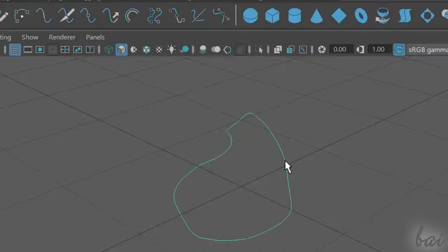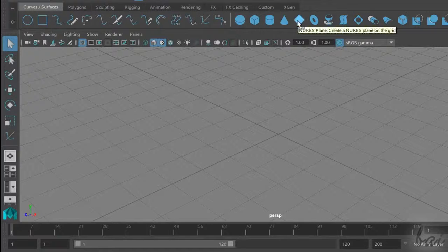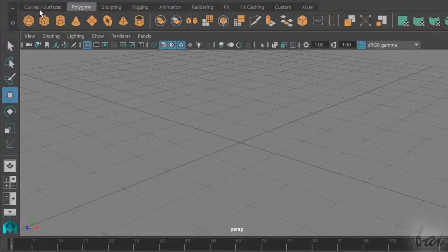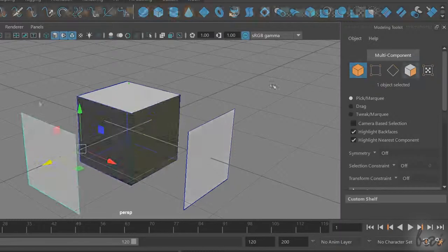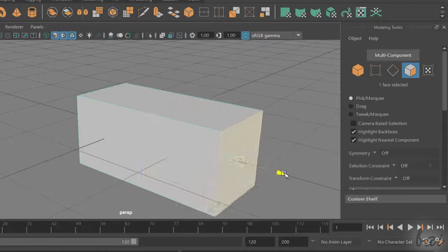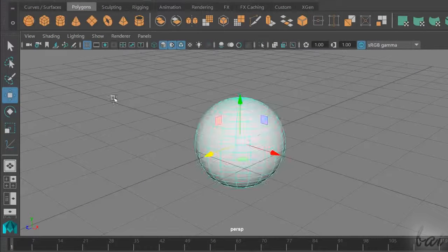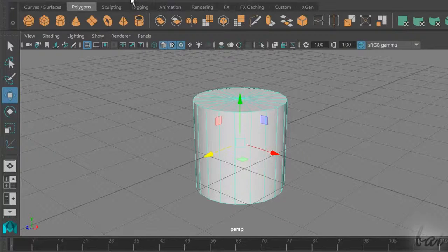You can also create simple planar surfaces. Select a closed curve laying on a single plane and click on the Planar tool. Planar surfaces are 2D objects filled inside. There are also the polygons or mesh objects to draw 3D objects. Differently from the NURBS, polygons are 3D filled objects with a surface and a volume. You can draw polygons through the Polygon section using the first group of buttons on the left.